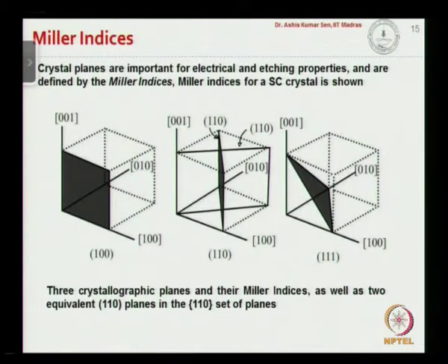When you talk about a silicon wafer, the crystal plane is very important for the electrical and etching properties. The electrical and etching properties of the wafer depend on the specific crystal plane, and the crystal plane is defined by what is called Miller indices.